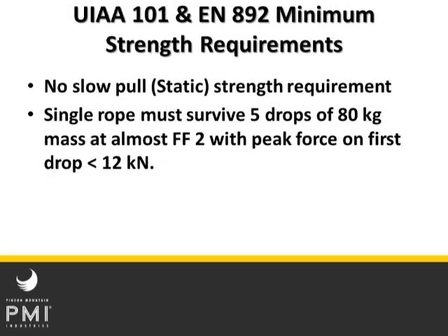UIAA, the Union International Alpine Association, the mountain climbing folks, have an international standard. It's a truly international standard for static ropes. I don't believe they actually have a slow pull static strength requirement. They do have these 5 drops, 80 kg mass, which has to have less than 12 kilonewtons.